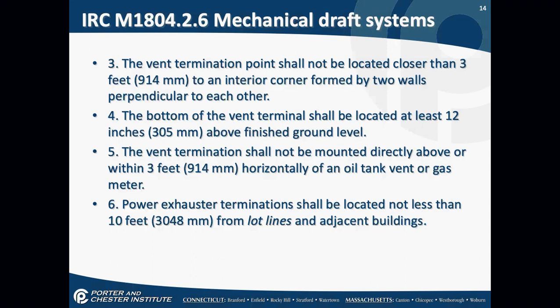Again, all of this stuff, if you think through why these rules exist, they all make sense. Number 4, the bottom of the vent terminal shall be at least 12 inches above finished ground level. In other words, the ground level after all landscaping, concrete, and everything else is done. Why do I care about that? You don't want anything getting in that vent, whether snow, debris, animals. Primarily, the reason is snow.